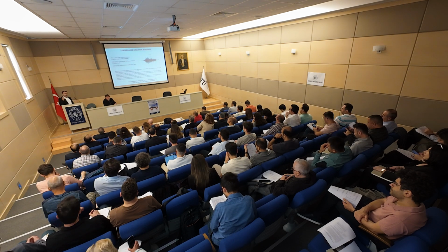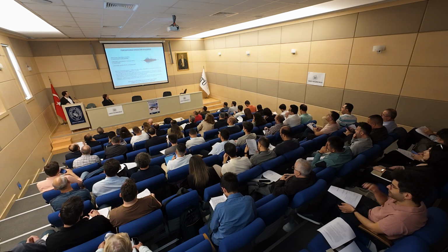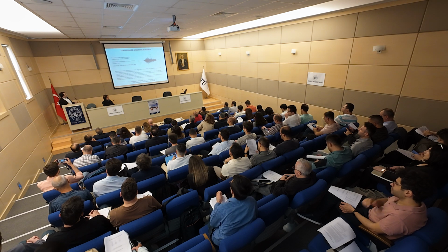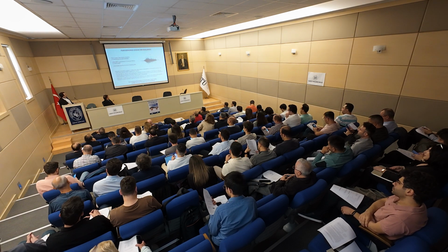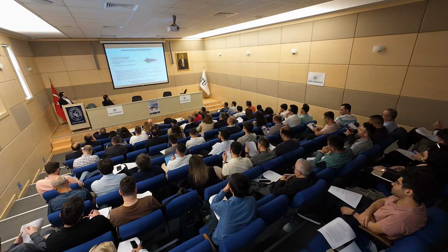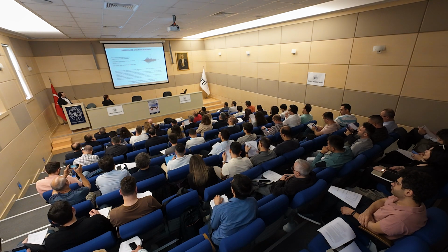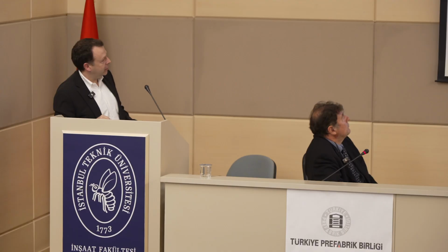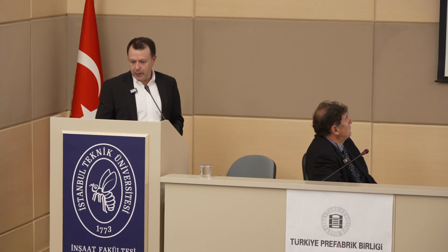Okay, so now that we have these 2 different designs, we want to do a performance check. We're going to show you some results of nonlinear time history analysis for both buildings. We're going to run them at the 100% MCE level, and we used ETABS to run these analyses, modeling the building moment resisting frames. And then, as I mentioned, these are the additional checks that we would have to do for the gravity system.